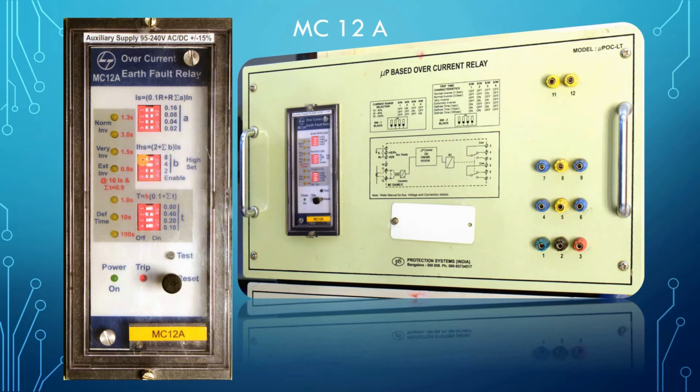Now coming to IHS. IHS is the high set current that I told you about. High set current means the instantaneous current limit. This high set current also has a formula that is written here: 2 plus sum of B, into IS. That means it is some multiple of IS. If sum of B is 0, this will be 2 times IS. That means minimum IHS can be 2 times the current setting. Let the current setting be 1 ampere, then this can be 2 ampere. That means if the fault current crosses 1 ampere, the relay will trip according to the characteristic set. Here the characteristic can be set using this SW2.